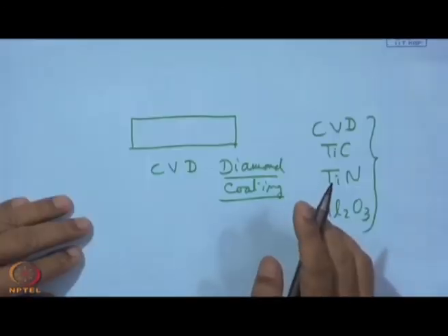With that roughness there are two problems. One, during machining of aluminum base alloy, the aluminum chip can get entrapped into those voids in between the crystals, that means in the valleys. And number two, when the flank surface of the cutting tool, which is not very smooth, rubs over the surface of the work material, though diamond is extremely inert, because of these high points it cannot give the expected surface roughness.